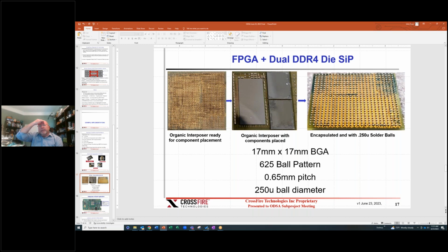Speaking of the current interposers, 130 micron pitch. Yeah, that's exactly what this technology was designed to implement. We've figured out a way now to handle those types of pitches, which are larger, believe it or not, than what we typically want to do on the die aggregating process. But this interposer had some really good electrical capabilities. I did all the signal integrity simulations and hyperlinks on it, and it is amazing.